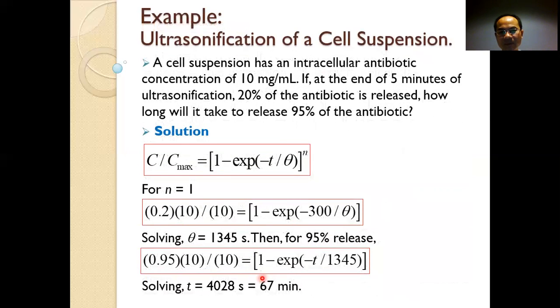This is the last slide that we talk about for cell disruption. As I told you, with cell disruption we would like to separate the desired product that is included in the cell, the intracellular product. For intracellular product, we have to separate the cell out of the liquid first, and then we rupture the cell. Then the cell will release the desired product. The next step is to separate the solid from the liquid released from the cell. We can separate solid by centrifugation or by filtration.